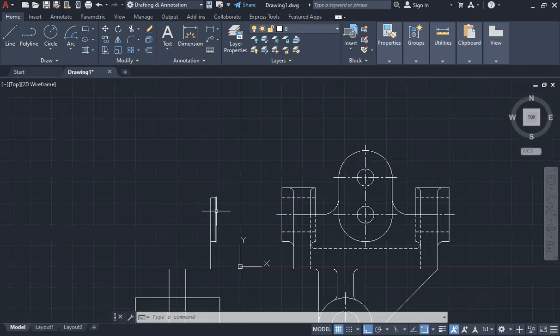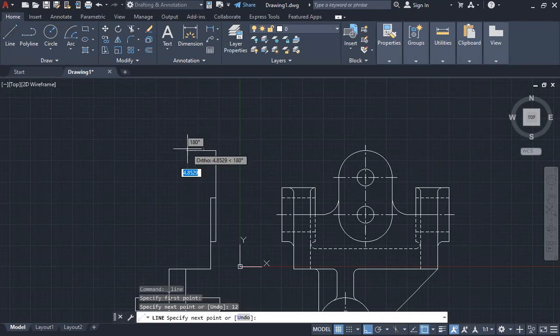And then I will extend this line a distance of 54. So 54 will be 16 plus 16 plus 22. So 16 plus 16, that's 32, plus 22 will give me 54. So I'll click on this edge, tap the tab button on my keyboard, and change this distance now to 54. So now this point here corresponds with the top of this slot. I'll draw a line across that goes 12 mm and comes down until it intersects with this point here. Then across and down.